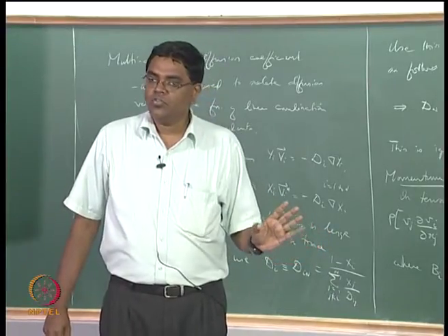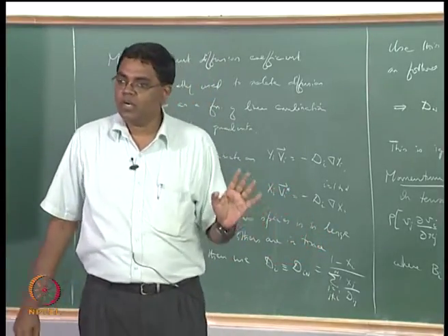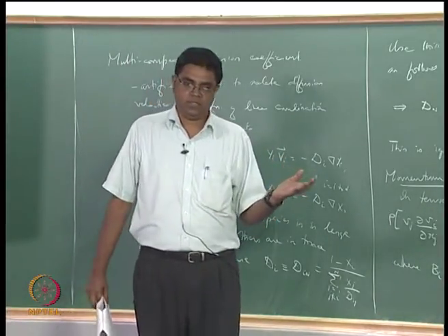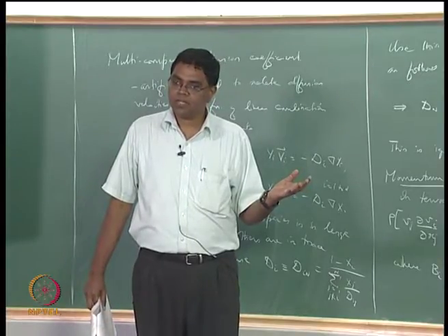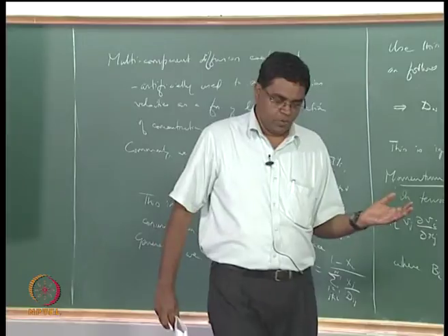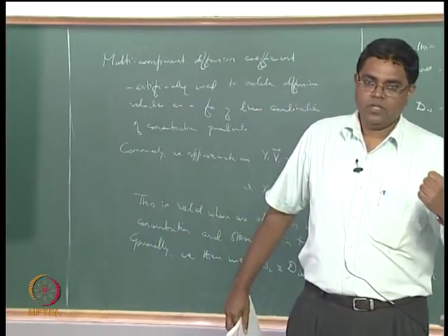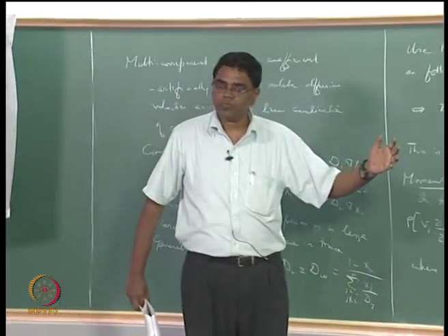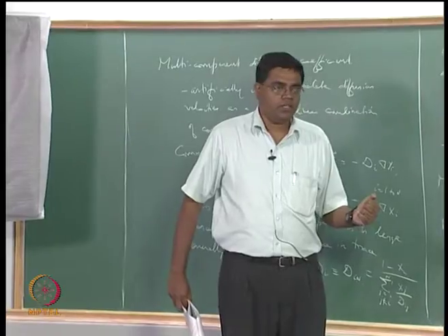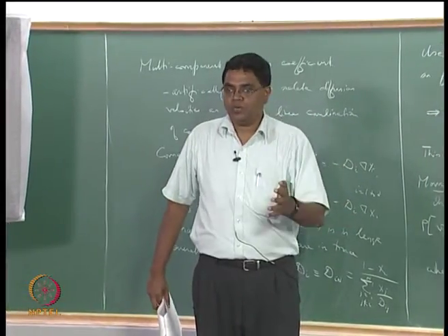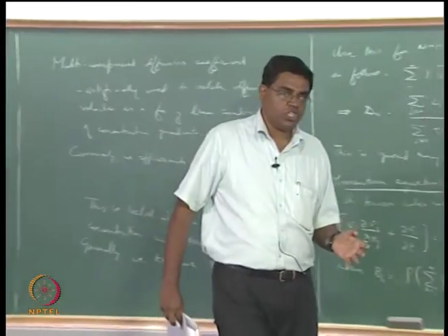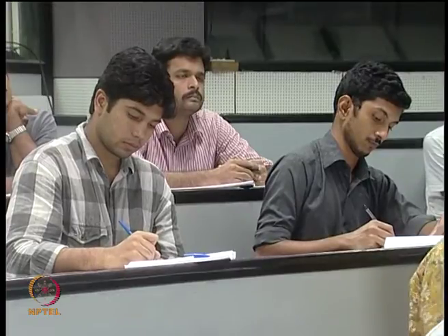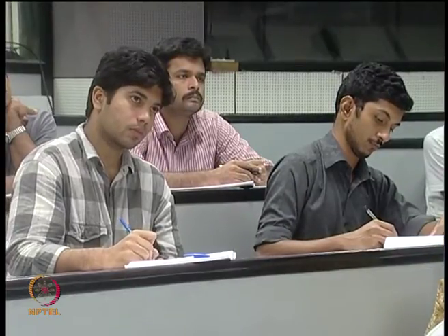One, maybe the mother of all equations, would be to write out an equation for the stagnation enthalpy, because the stagnation enthalpy will take into account the kinetic energy involved in the motion of the mixture, and it will also involve the pressure work, because we would now say h equals e plus p by rho, where e is the internal energy and p by rho is the pressure and density.